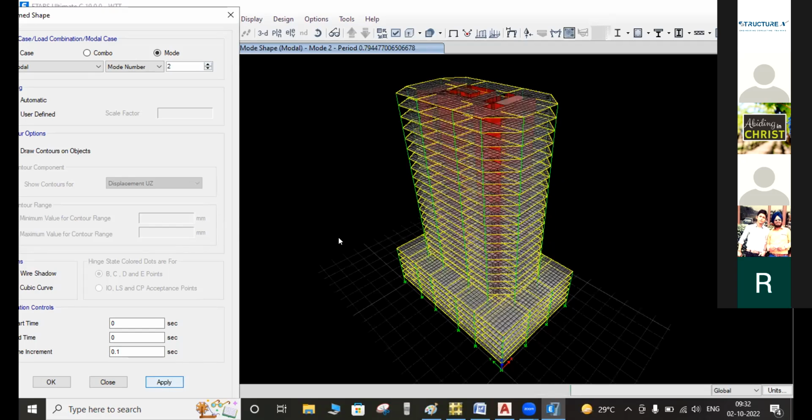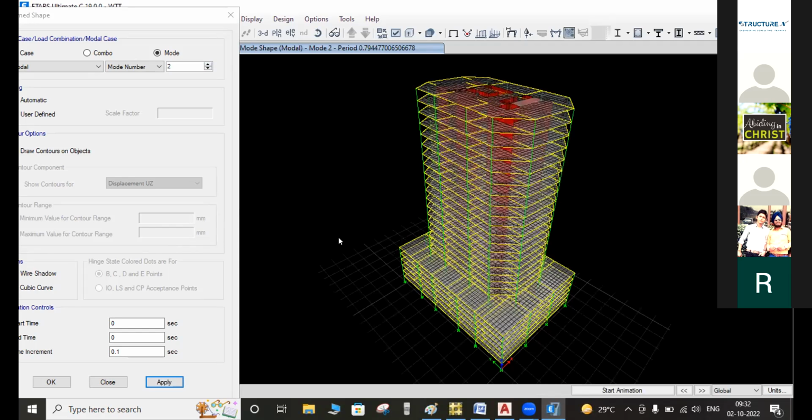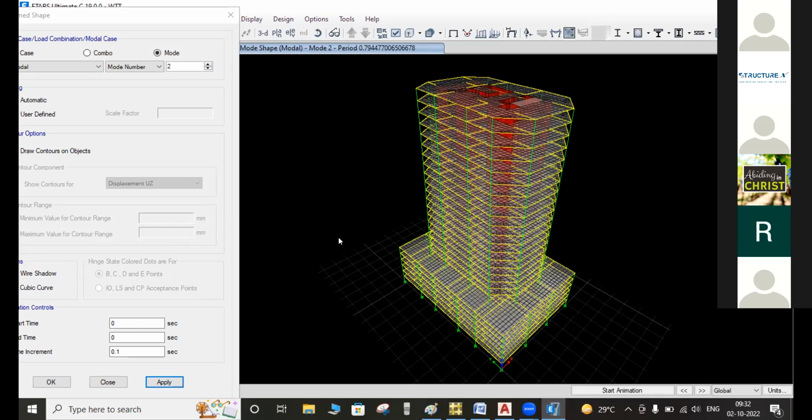Right, sir. Basically, with the help of stiffness, we are controlling the behavior of the structures. It depends upon the vertical members, like the columns and walls. Bracing is also used to control this. The positions, section sizes, spans, and the orientation are also controlled, which is what we call stiffness, a very important part to control as early as possible. Moving on to the dynamic analysis, we need to revise the framings, as we have already applied the loads and deleted some framings. So we perform this task in the modal analysis as early as possible, which is helpful for the torsional regularity and also for the storey regularity.